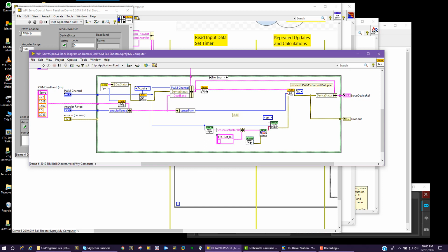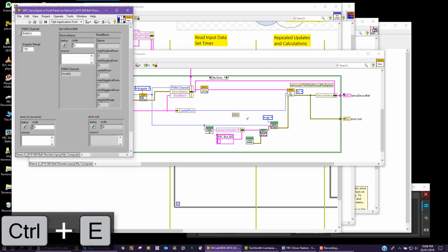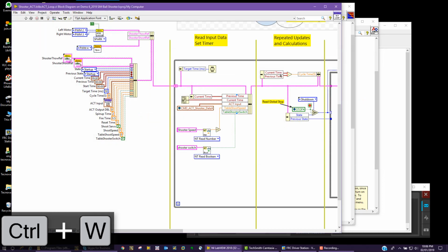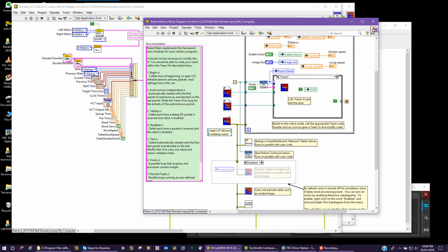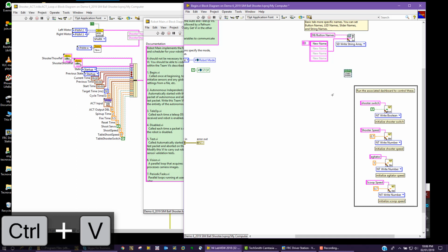So I'm going to take this VI and I'm going to copy it. So again, in any open, servo open, sensor open, there will be this simulator start engine. And let's just grab it, and then we're Control C, we're going to copy it. And I'm going to put this in begin. Close all these other ones. Go to my robot main, open begin, and we're going to paste the start simulator engine in the begin. And that should fix the problem.